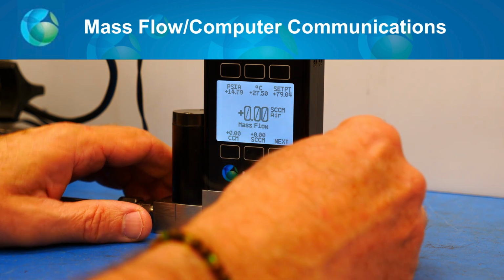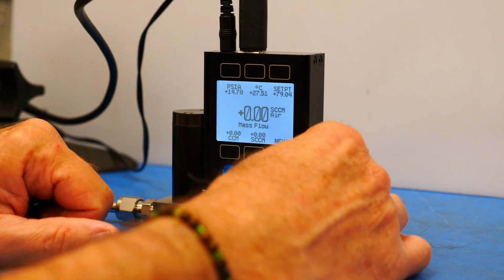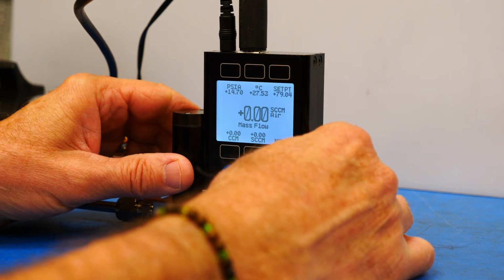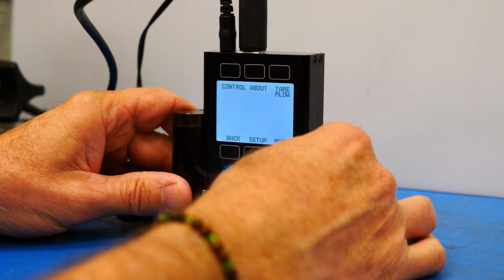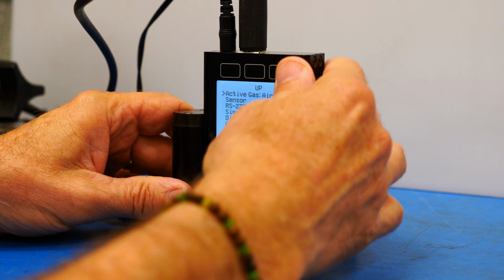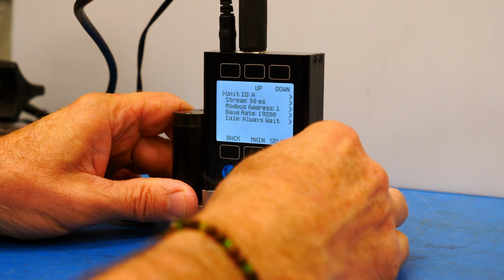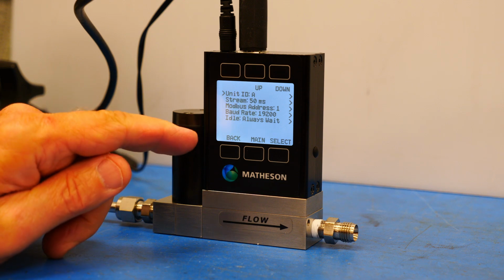I'd like to show you how to set your device, or in other words, to check the device to make sure it's set properly for serial communications. How you would do that, you would press Next twice, then go to Setup, and then go down to RS-232 Serial and select. And here you can see it gives you information, your unit ID,